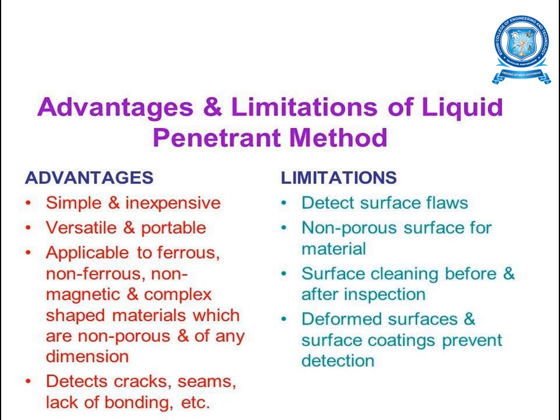So coming to the advantages and limitations of liquid penetrant methods. The advantages are: the liquid penetrant testing method is simple and inexpensive. It is versatile and portable. It is applicable to ferrous, non-ferrous, non-magnetic, and complex shaped materials which are non-porous and of any dimension.